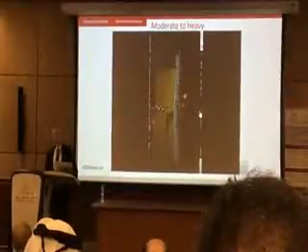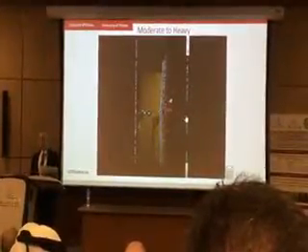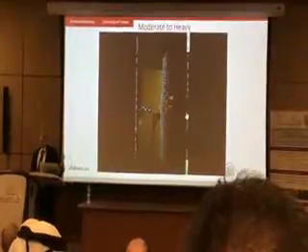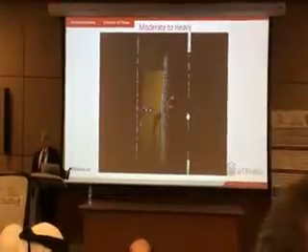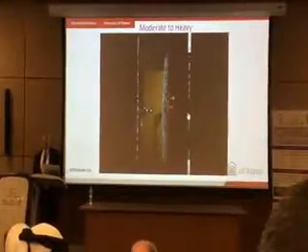It has a little bit of permanent deformation, but it can possibly be repaired. So this is B2 performance level. You see, these observations are linked with response quantities indicated as B1 through B4.